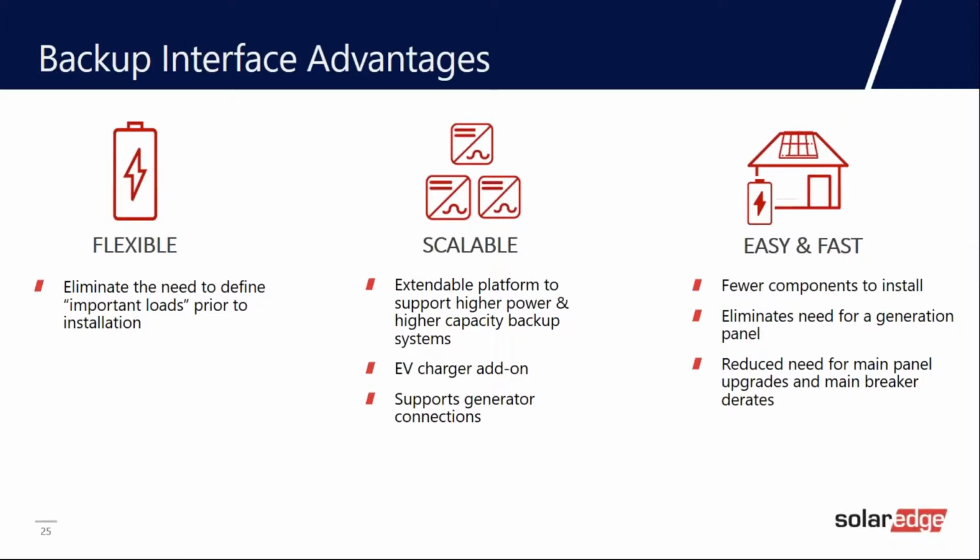It supports generator connections. I'm going to use the words easy and fast very loosely. The reason I do that is because if you have a home that has a combined meter main, which is very common on the West Coast, it's a little bit trickier. But if you're on the East Coast, then your meter is typically separate from your main distribution panel, so the installation is relatively easy.